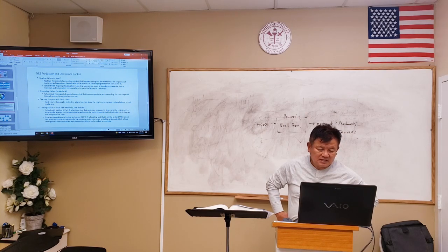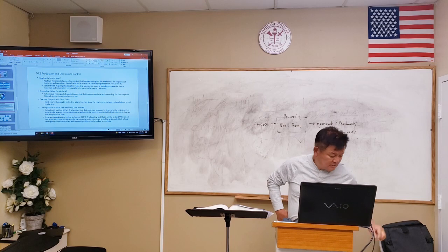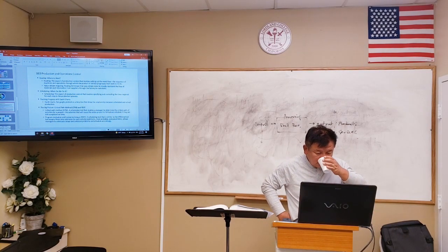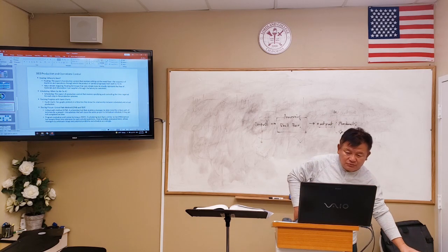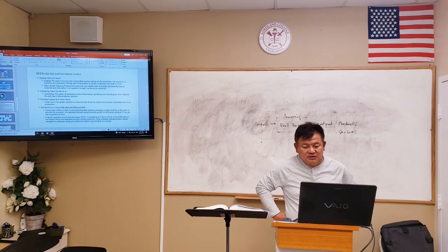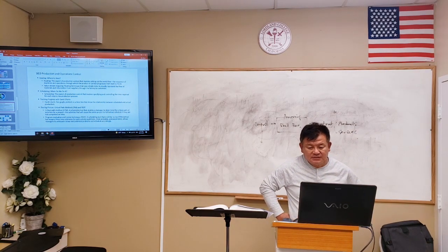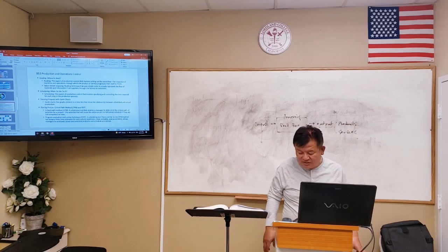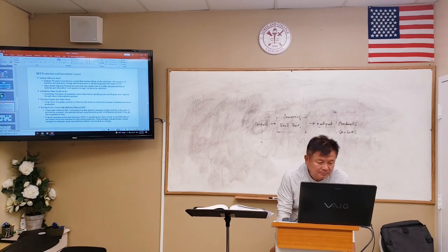Routing means the aspect of production control that involves setting out the workflow, the sequence of machines and operations through which the product or service progresses from start to finish. This is all the procedure we call routing. And value stream mapping, routing.